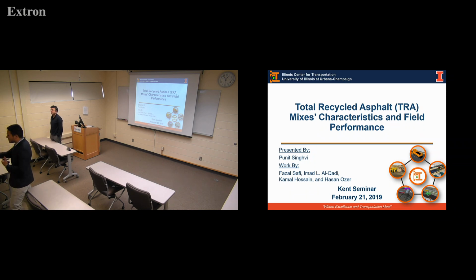I cannot confirm that with DIC because we cannot see that level of detail. But we can see from the strain field that something similar is happening. This crack, instead of going fast and straight, is branching and branching. Maybe the airvoids are just causing the change in the path, or something else is happening there. But we are limiting ourselves to mentioning that there is a more branched structure that is causing this behavior.